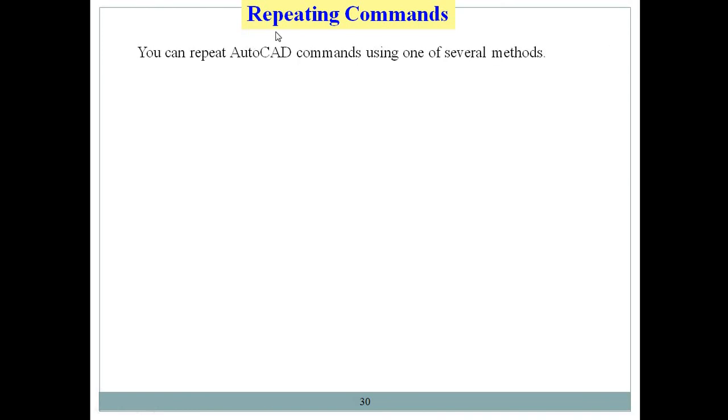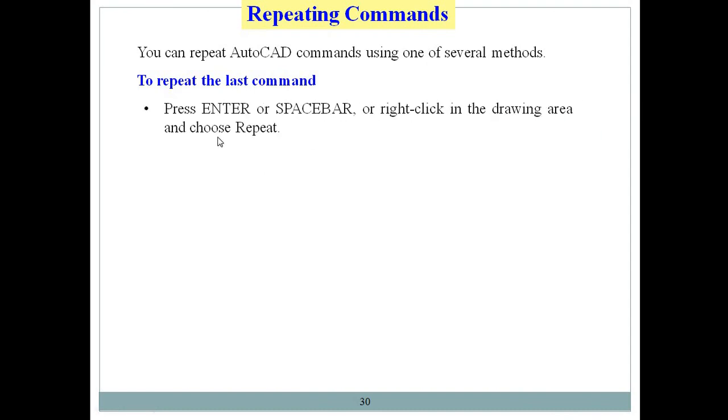Next point is repeating commands in AutoCAD. First one is to repeat the last command. Then press enter or spacebar, or right click in the drawing area and choose repeat.